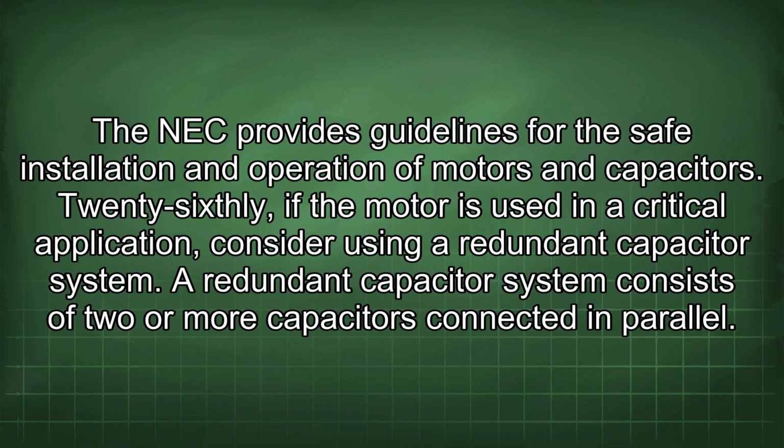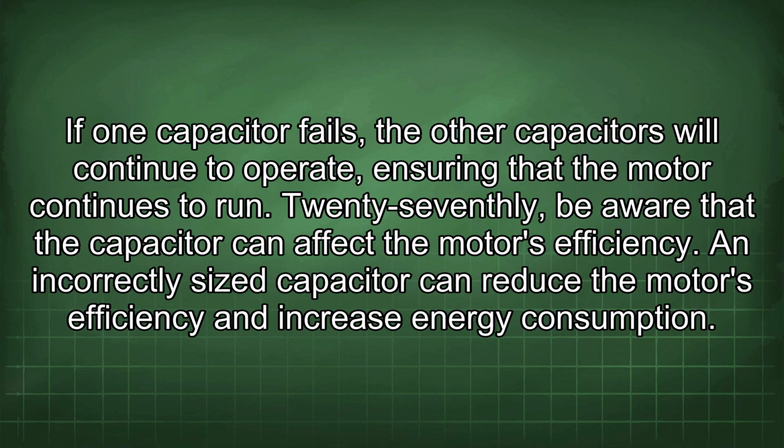26th, if the motor is used in a critical application, consider using a redundant capacitor system. A redundant capacitor system consists of two or more capacitors connected in parallel. If one capacitor fails, the other capacitors will continue to operate, ensuring that the motor continues to run.